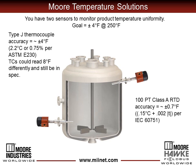Two RTDs could differ by as much as 1.4 degrees Fahrenheit while reading the same product temperature, and that is way better than the 8 degrees difference that we could have had with two type J thermocouples.